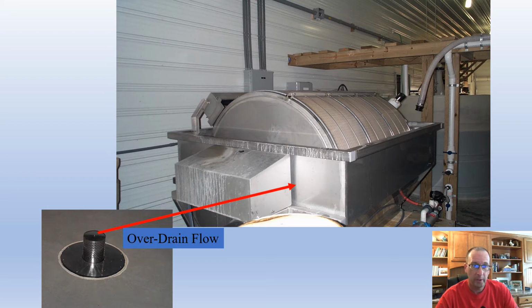One of the things that we can look at for sure is the way that the microscreens interact with the surface of the water. As the drum rotates around, the small particulates get stuck in this small membrane and they're dragged from the water column. Therefore, they stay out of the system and the circulating water continues through. In the next slide, we're going to look at a picture of one of the microscreens up close, and you can see the quantity of material that they can pull out in a single pass.